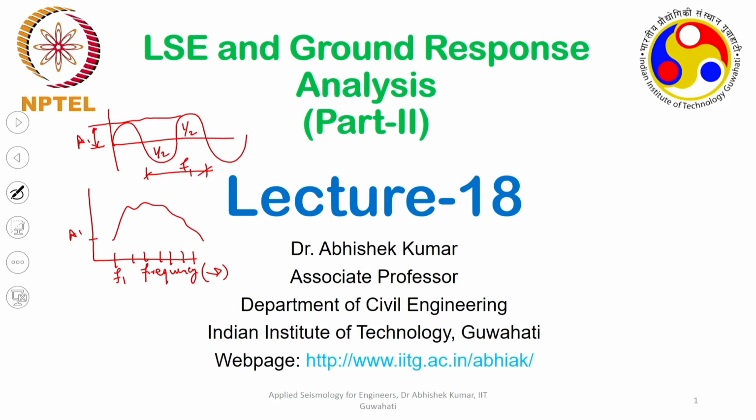So, if you take any particular motion, this is the frequency content of the harmonic motion which is present in this particular random motion, and corresponding to this is the amplitude of that motion. So, based on Fourier spectra or Fourier analysis, you can find out how many harmonic motions with different operating frequencies are existing in a ground motion.